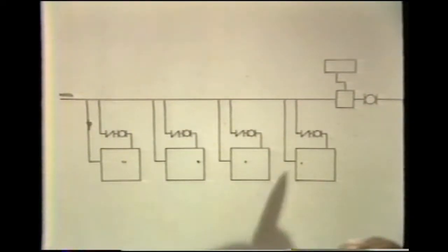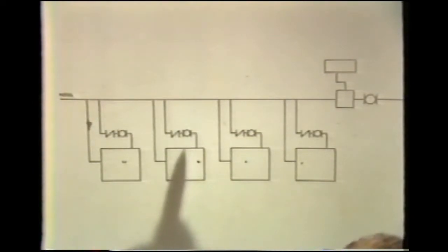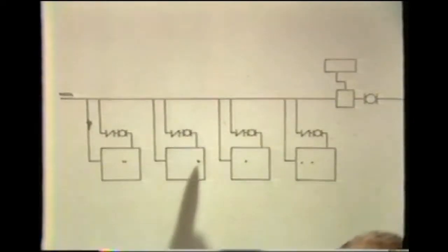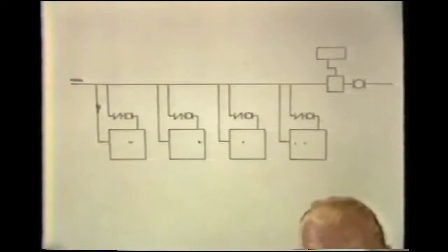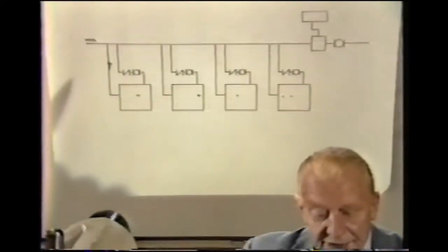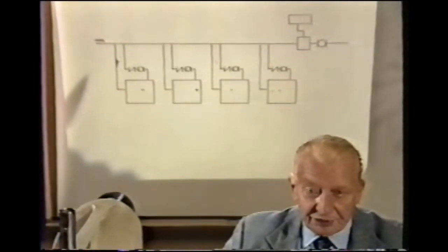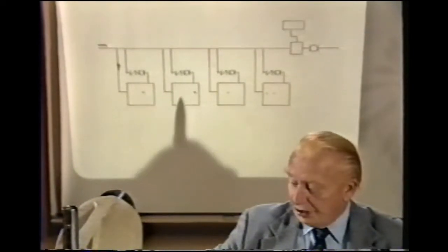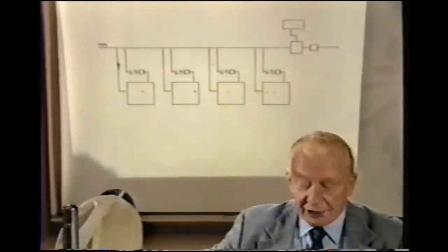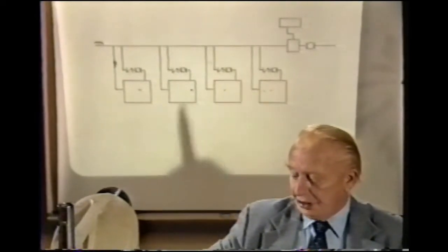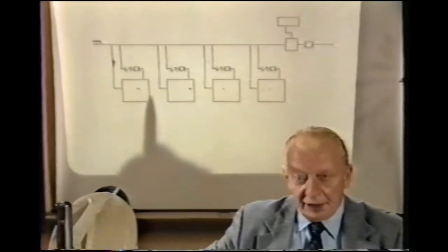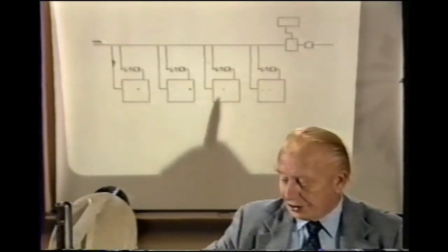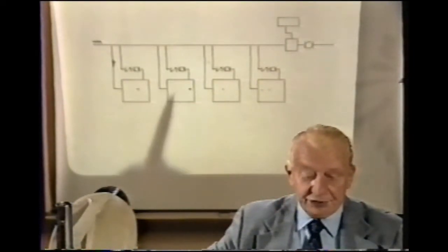The basic advantage of breaking the large system down into several smaller units is that the large, oversized single boiler unit establishes a very low seasonal efficiency, because of bypass stack losses in the boilers during low load operation. In this circumstance, because the boilers are relatively small, the stack loss is decreased, and because of the reduction in stack loss, we do establish a very high seasonal operating efficiency.